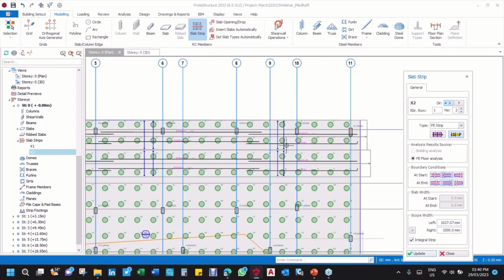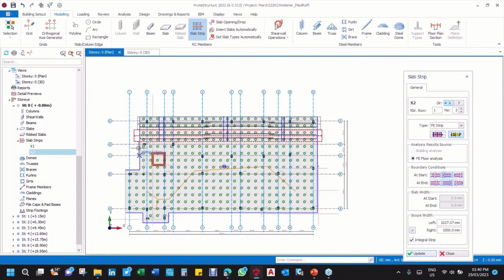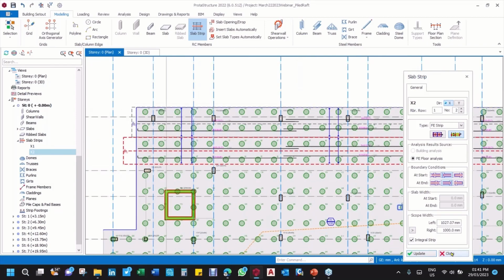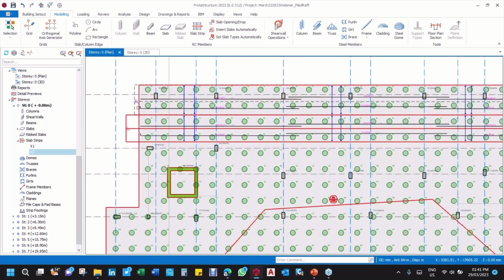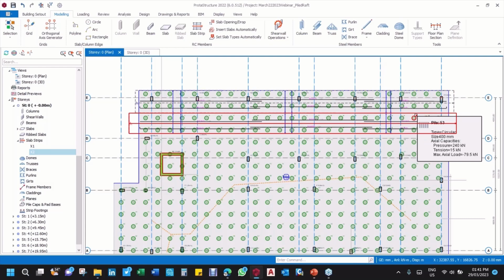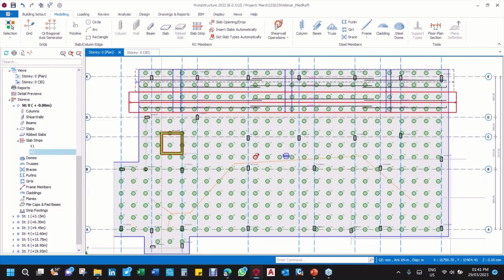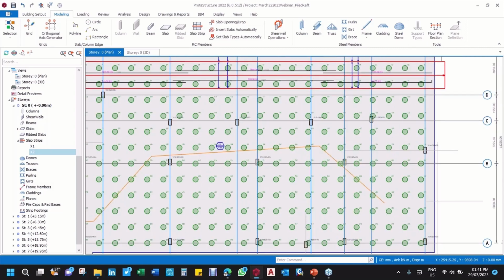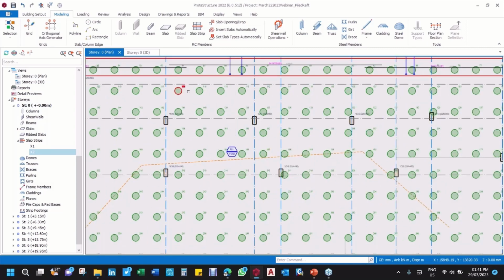The other thing is also advisable to use one strip for similar thicknesses. In a situation whereby you have different strips with different thicknesses, and I want to believe that one of these days we are going to be treating that too, in order to make this more economical, we can come here and say the slab under this column should be a particular thickness.